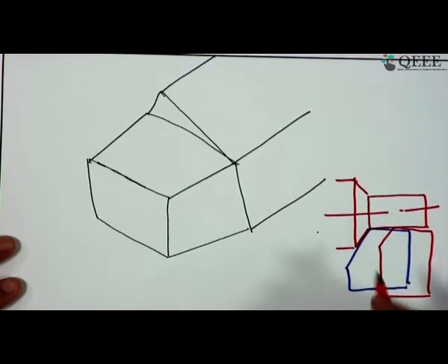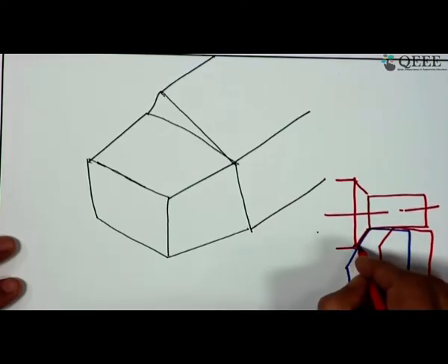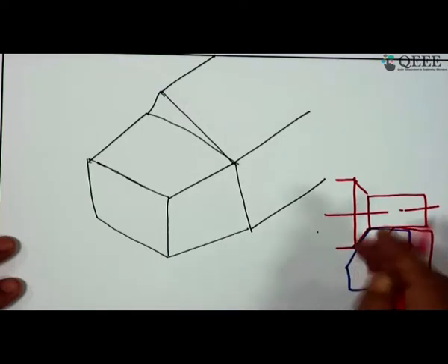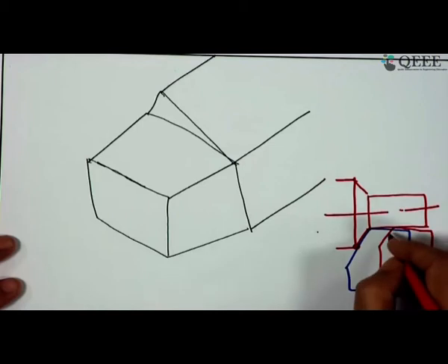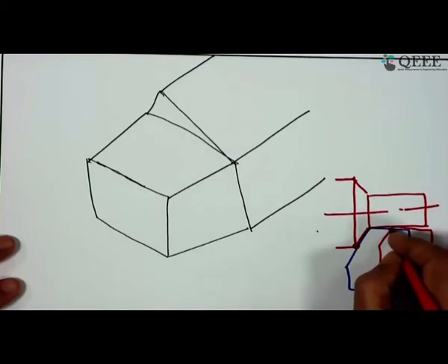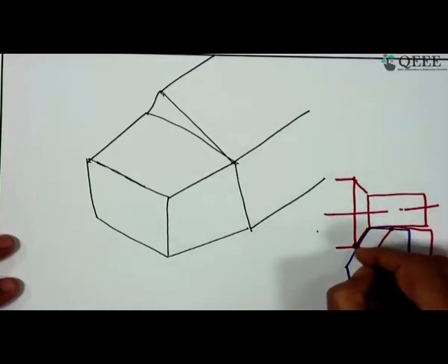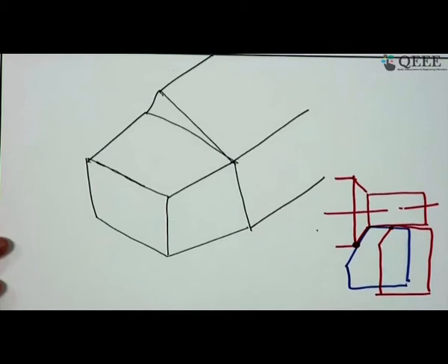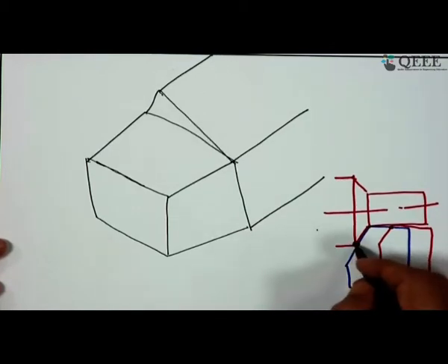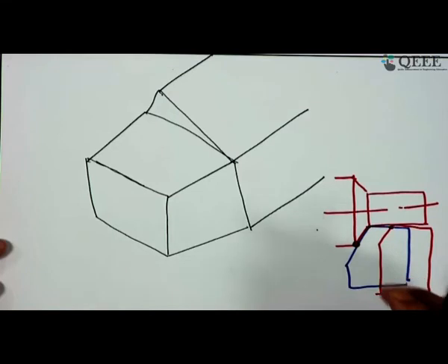What I mean to say is you have this border line, this point is located at the border, and beyond that there is no material. Similarly, here we have one border. So, what is the significance of this border? Actually, this point is very sharp, it is strain hardened. So, this point virtually acts like a cutting tool on the original cutting tool.